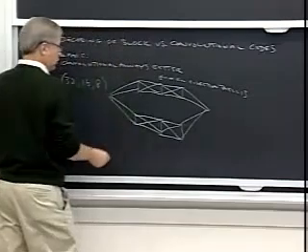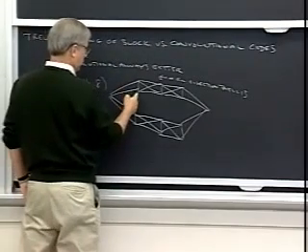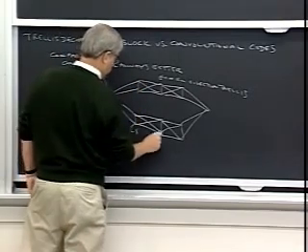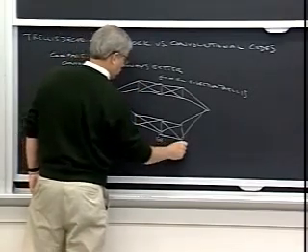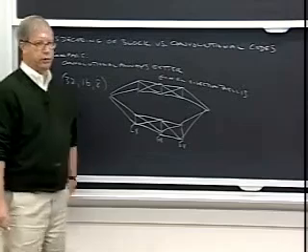And for the (32,16,8), it turns out you get kind of 8 parallel sections like that with 8 of these each. In any case, it's 64 states at each of these boundaries. All right. So you could say it's a 64-state trellis.